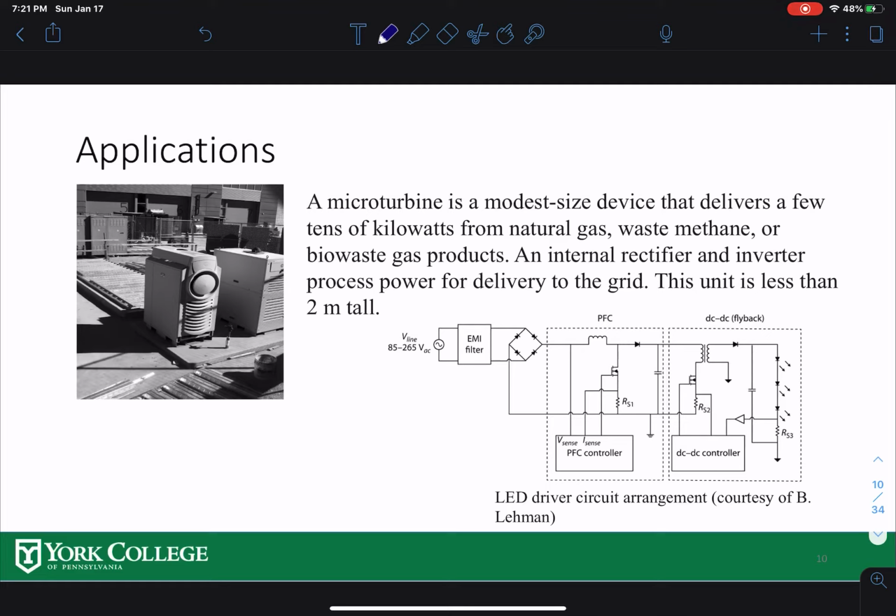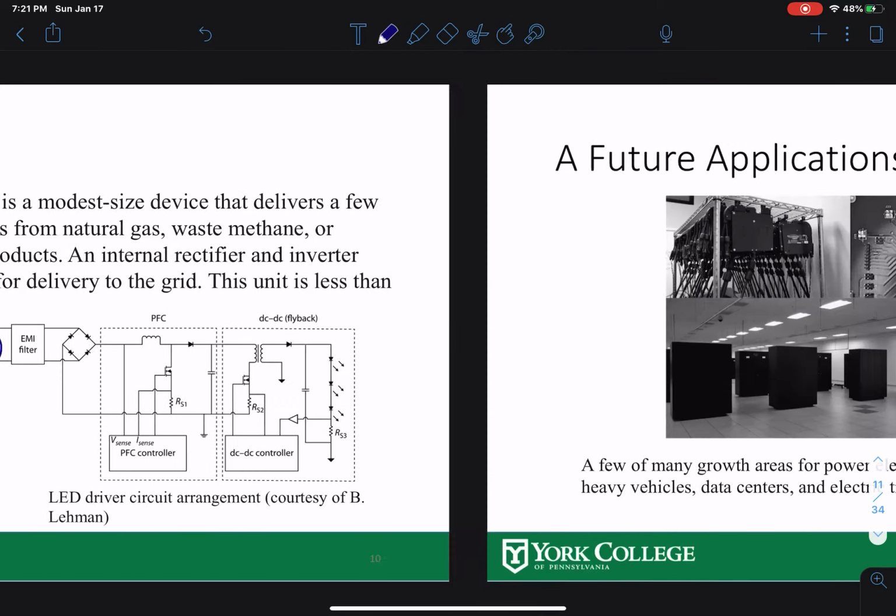And one small scale application is a mid-sized micro turbine, right? It can use the heat coming out of any big building, or it can be used for a geological site. Those can produce around 10 kilowatts. And basically everything is there, inverter, rectifier, everything inside that, because your incoming source is variable, you have to make fixed voltage, fixed frequency. So everything is inside this little box over here.